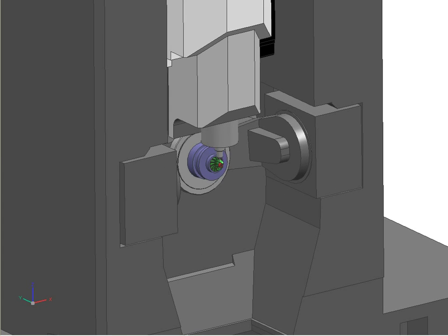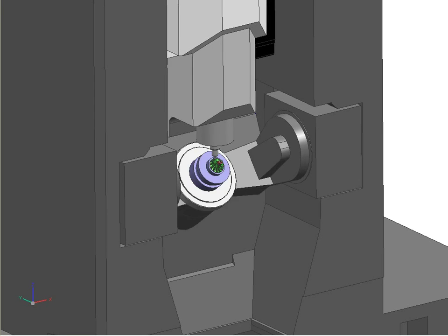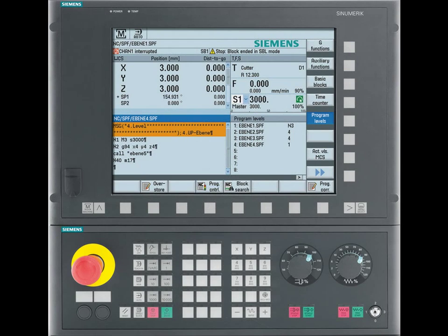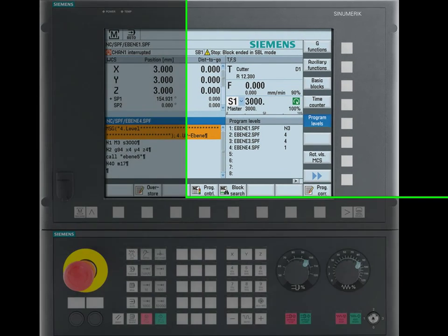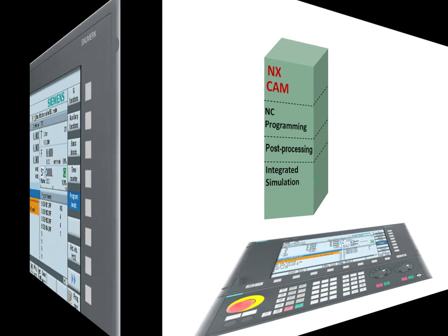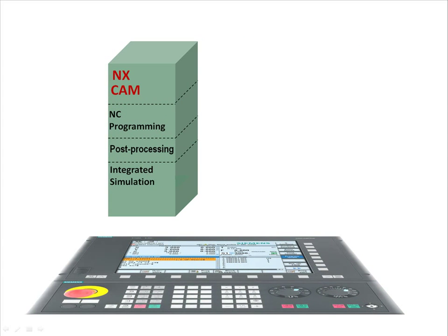The accuracy and completeness of the simulation is only as good as the software used to interpret the G-codes and convert this to 3D motion. For machine tools fitted with Siemens Sinumerik controllers, we can offer a special way to address this. NXCAM can use software from the real Sinumerik controller to drive the machine tool simulation. With this option, the motion of the 3D machine model, including the effects of cycle commands and special codes, is as complete as is normally needed in a machine tool simulation.